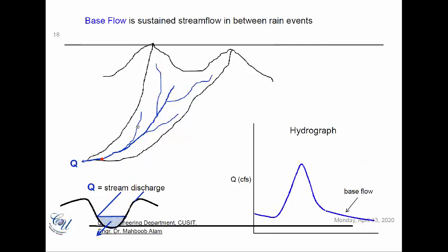And once almost all the catchment has drained, even the water that has fallen on the furthest area of the catchment reaches the outlet point, again we would be in a normal situation and the base flow would start again. So we would be again more or less equal to the point where the discharge started increasing. So these are three different parts of the hydrograph.